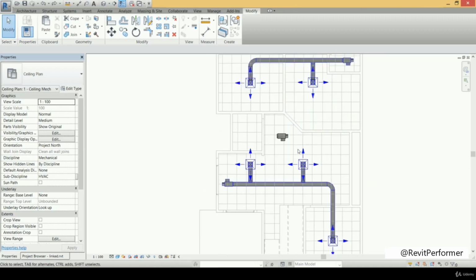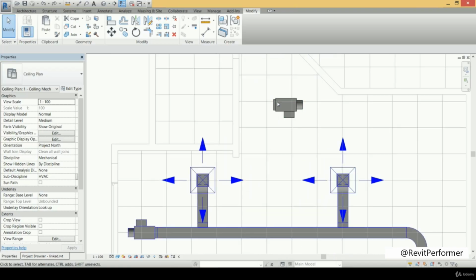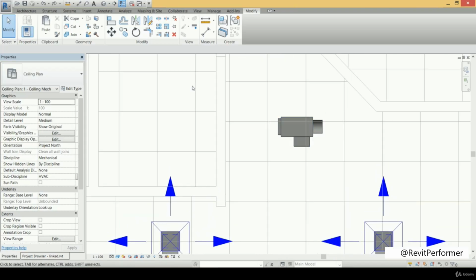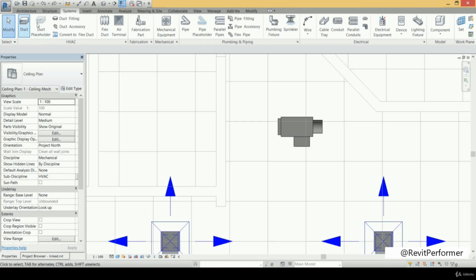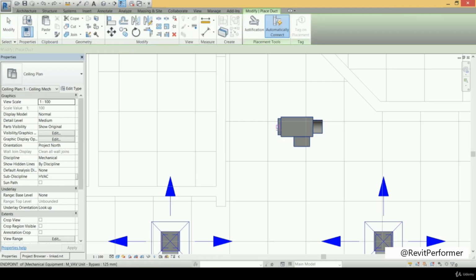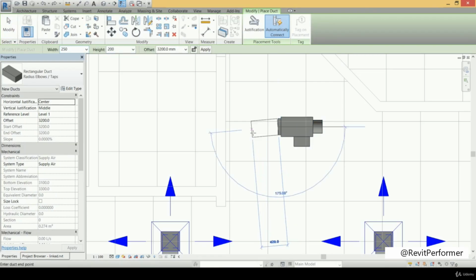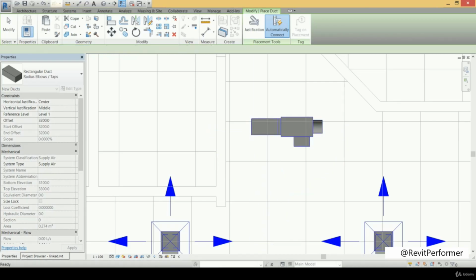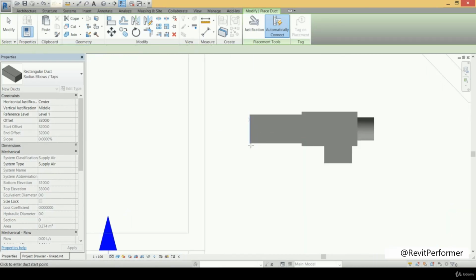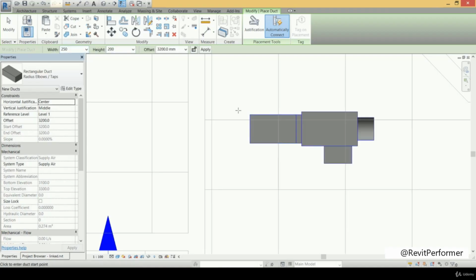And also another note is that if you reach the end of the duct, for example, I can make a duct here. I go to the system and duct and start from that point to that point, for example. So suppose, for example, this duct will be ending at that position, but this duct is an open one, and we need to close that duct.